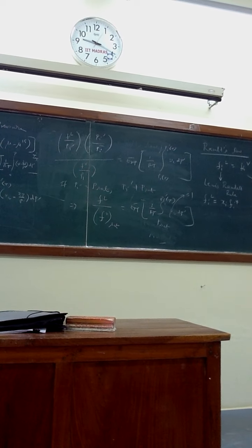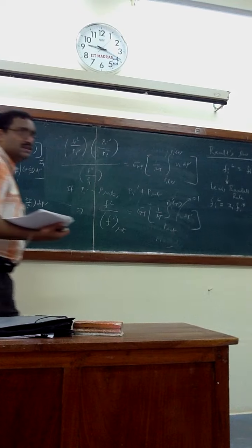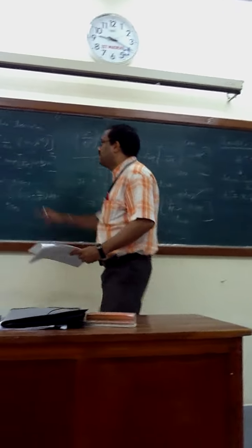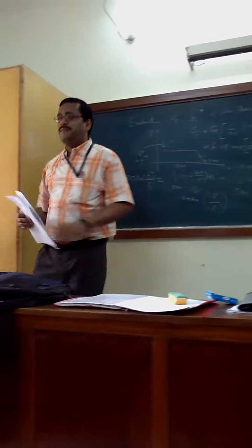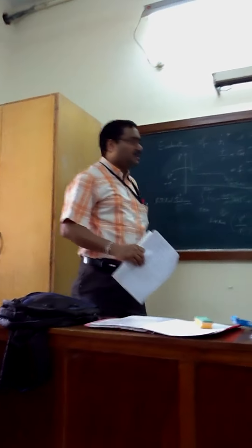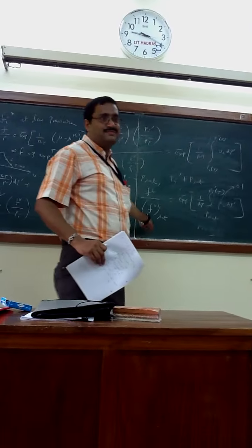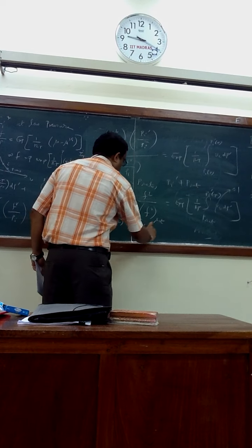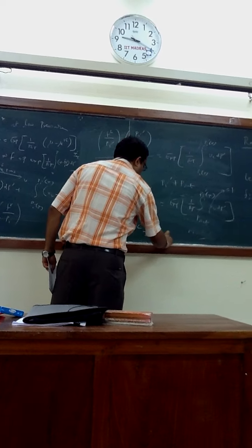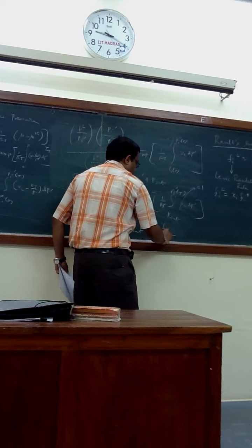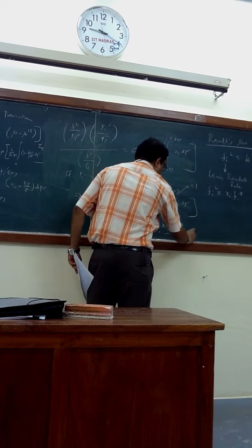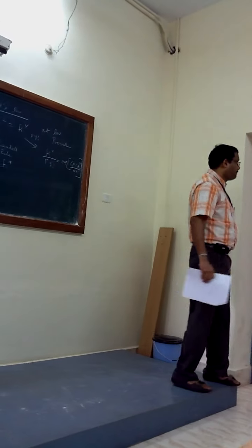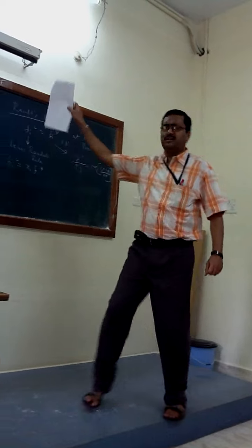And FB sat is a vapor phase. At low pressure, from this expression for the vapor phase, FB equals P, which means FB sat equals P sat. So at low pressure, FL equals P sat. That means Fi star equals Pi sat. That's why I told you yesterday. All this I have done earlier in the class.